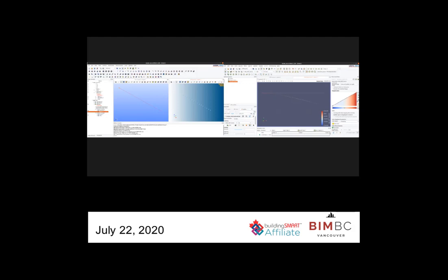And this is a single beam being analyzed in open source software called Code_Aster. But the beam actually comes from an IFC file. And some people don't know this, but IFCs can store structural analysis models. It can store structural curve members and point connections and loads, and store the results of the structural simulation back in the IFC model.